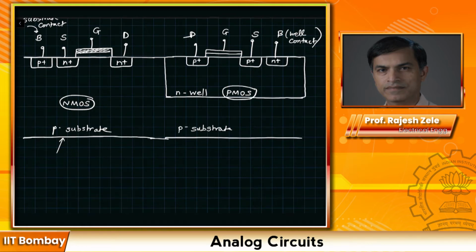I'm going to show you how to draw the symbol for the NMOS and PMOS transistor. I'm drawing the transistor in a horizontal manner because that's the way the cross section looks, and it will be easy for you to correlate to that. So in this case, we say this is our current flow, this would be your source region, this would be the drain region, and this would be your gate. And you show this line like this as a bulk connection or a body connection. So this would be our NMOS transistor.